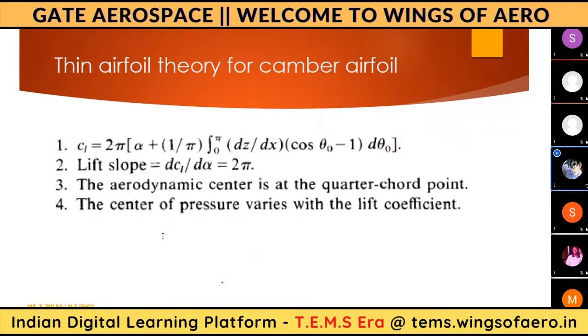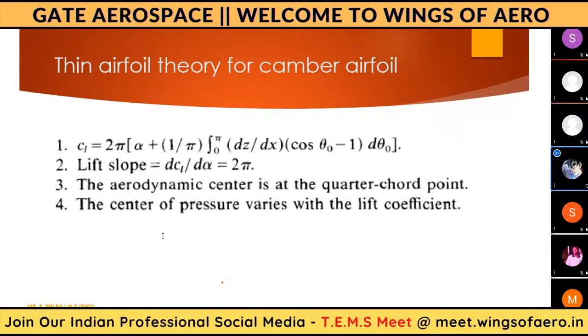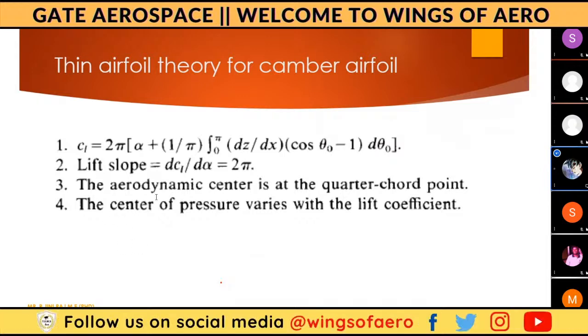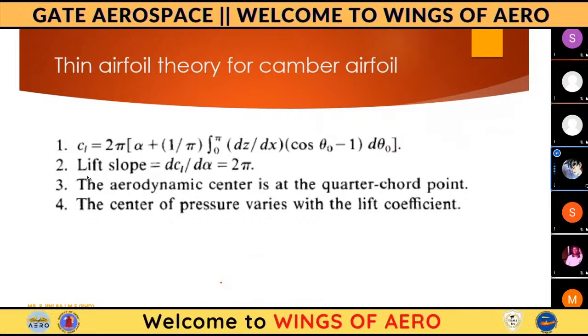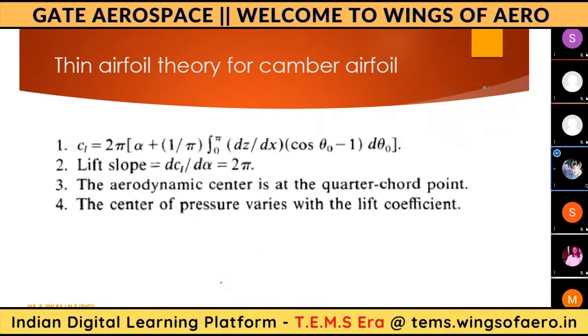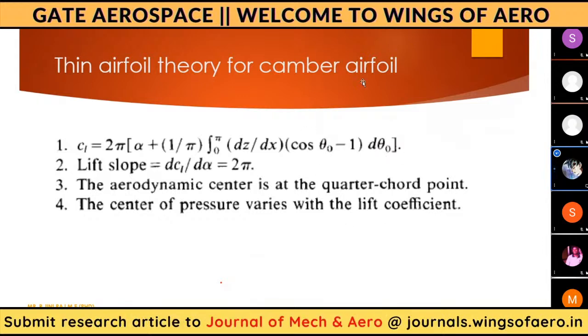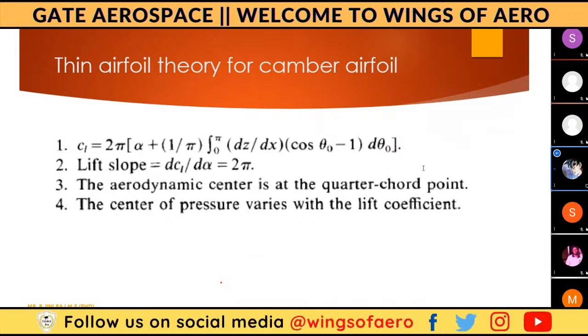In the same way, the lift curve slope, as I told in the last session and explained in this session also, whatever the aerofoil may be, it won't change. It will be constant for all aerofoils. Another important result is that the aerodynamic center is at the quarter chord point, which we all know. But the center of pressure varies with lift coefficient, because when the angle of attack changes, lift changes, so the center of pressure is also changing.